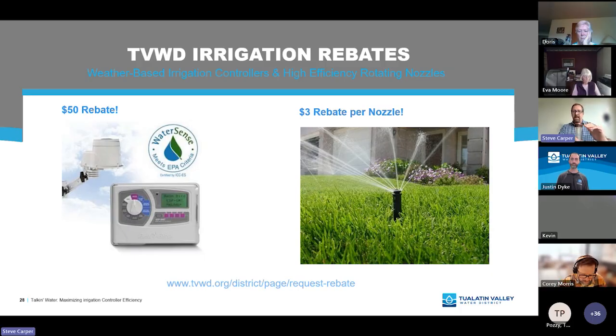Not down in. You really want it to be right there, because sprinklers sink over time. This is a common issue that folks face, and that I often encourage them to address when I'm doing assessments. In time, sprinklers tend to sink down into the soil. And what can happen when that occurs is that the pop-up mechanism becomes dirty and compromised, and if it rises and goes down and rises and goes down, soil and debris gets down into that shaft and can make it a little more sticky, and sometimes the stem does not then retract all the way,